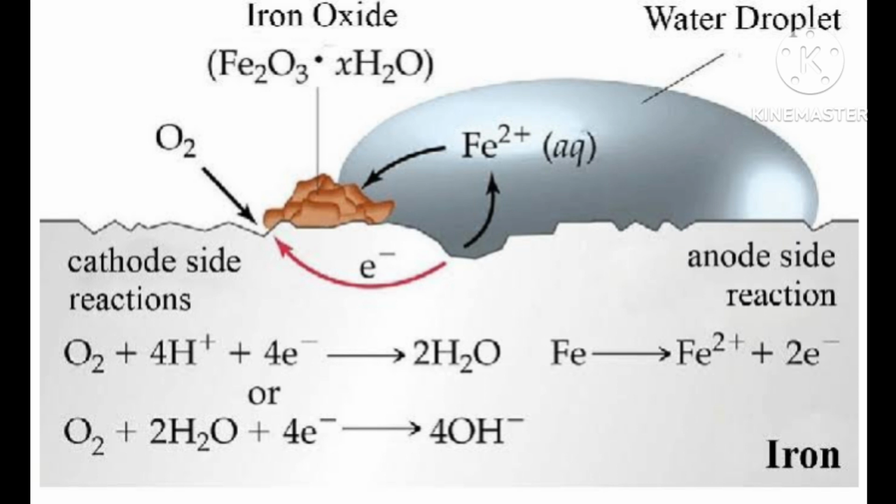If it is a wooden door, you are putting different types of paints. But particularly for metal I am talking here now. On metal also, the first coating will be a primer, one solvent will be there, and after that paint will be there.